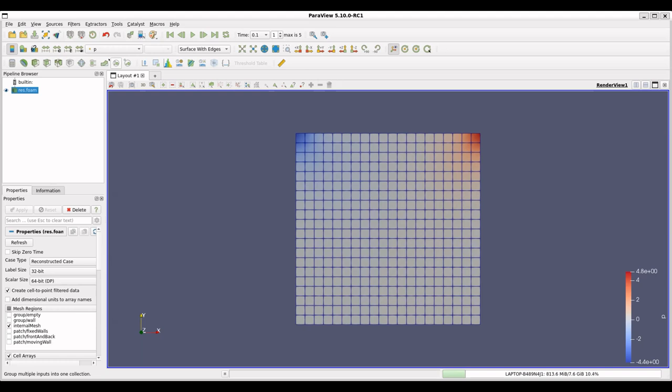Yeah, so my question was this: for example, I want to do the time series analysis, right? Time series analysis of what? Let's say how at a point the velocity field is varying. So you want to take a probe here, and you want to get the velocity value there, and plot the time history of it with time. Exactly. You can do it in ParaView. There is a filter called Probe. You can choose the coordinate, and then you can run the animation of how the course evolves. Yes, in ParaView you can do it. So if you load your data in ParaView, you can.